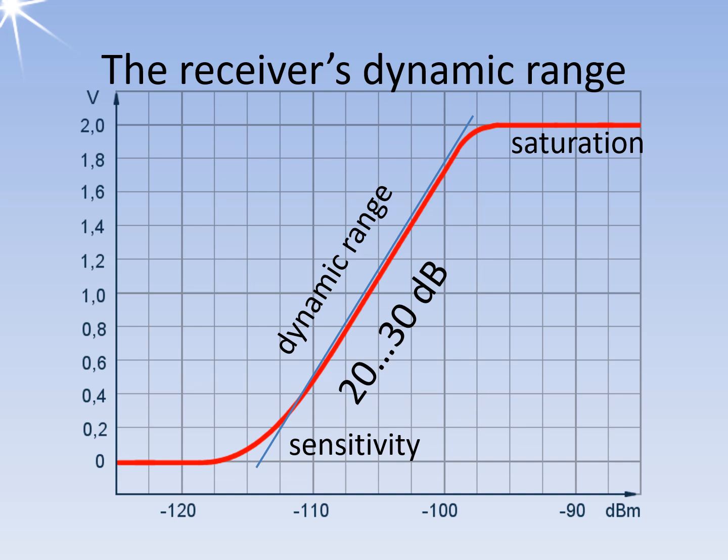In radar receivers, we encounter both extremely weak echo signals, often as low as a few picowatts, and very strong signals from nearby sources that can reach microwatts. This wide range of signal strengths can cause the receiver to saturate. Saturation occurs when the receiver is overdriven, resulting in a distortion of the signal shape. The maximum amplitude and signal edges may no longer maintain the correct ratio. This distortion leads to a loss of information, and a weak echo at the same distance may become undetectable.